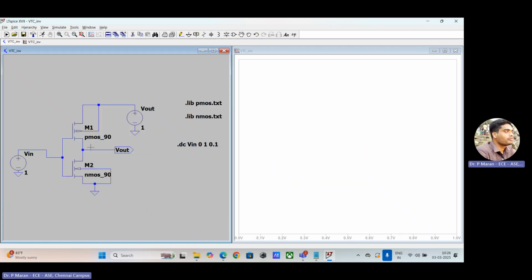Now I am going to measure the voltage. So I don't go for this type of button because that tool is for measuring current. Now your job is not to measure the current. Your job is to measure the voltage. Correct? So where you have to measure the voltage, this is where I'm going to measure the voltage. You see the red color pointer is there. The output variable node is available over there. Click, go there and click the voltage.